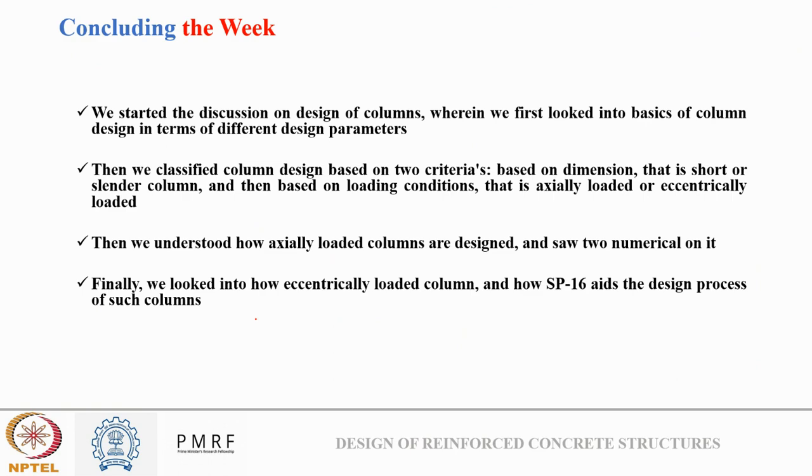So I will just conclude the discussion here. We started the discussion on design of columns in today's live session, wherein we looked at the basics of columns in terms of different design parameters. Then we classified column design based on two criteria: based on dimension, that is short and slender columns, and based on loading condition, that is axially loaded and eccentrically loaded columns.